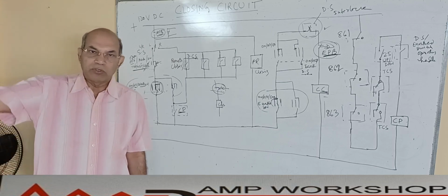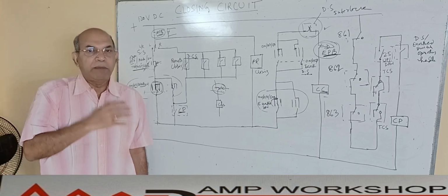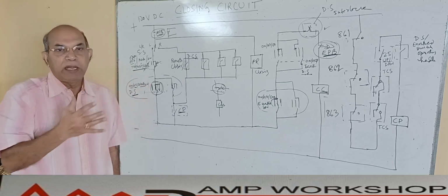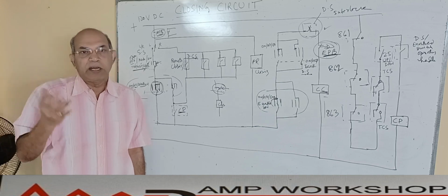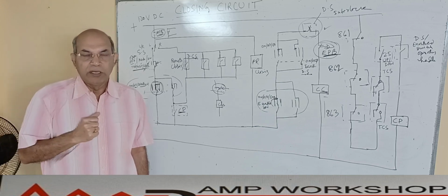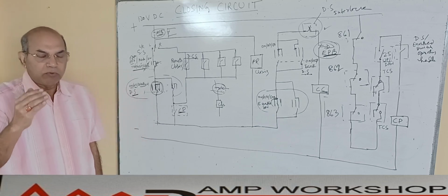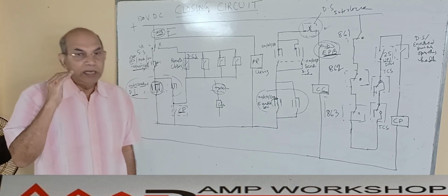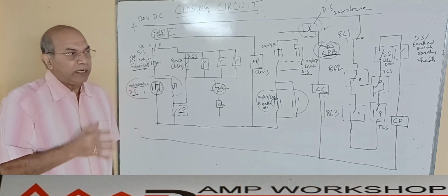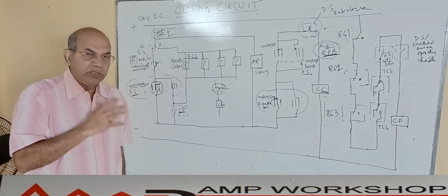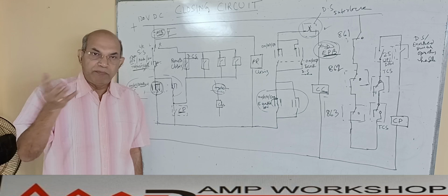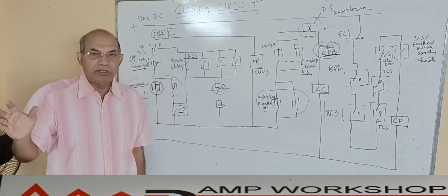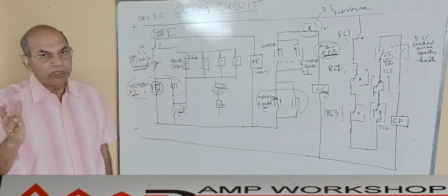But when I am remote, I am not near the switchgear, I am not aware of the condition on the switchgear panel. So in that case, remotely, through the intelligence, I have to make sure everything is alright. That means, when I am closing the breaker from the remote, I need to know that the entire closing and tripping circuit is healthy, and the breaker is ready to trip. If we close it and there is any abnormal condition in the system, the breaker will immediately trip upon closing.